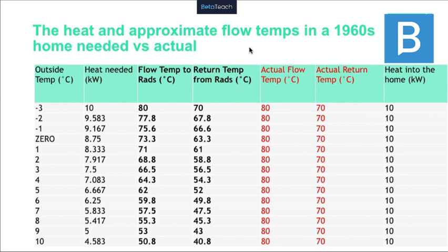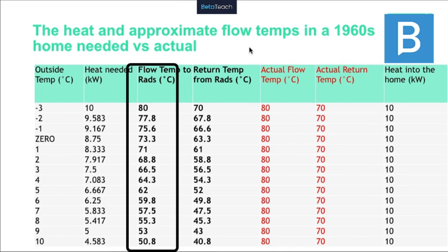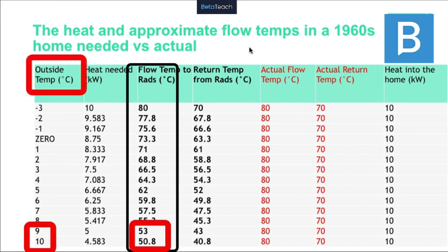So your flow temp can go down, and it's always been able to go down whether in an old house or not. So we've always been able to heat houses with low temperatures. Maybe not when it's really, really cold, but as we start to get warmer outside, we can heat all homes with low temperatures. That's just the law of thermodynamics.